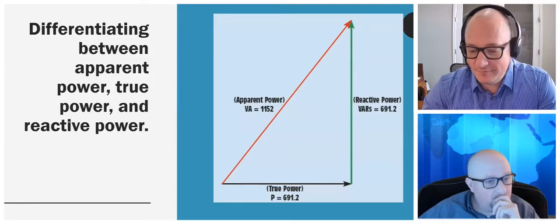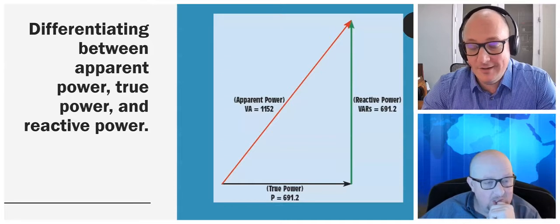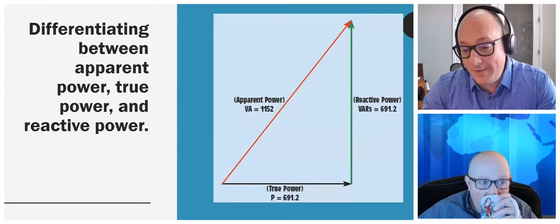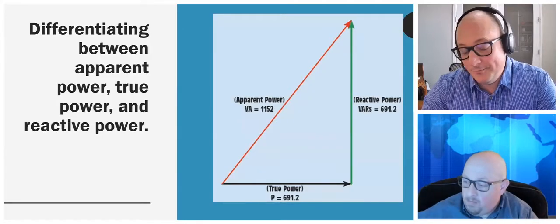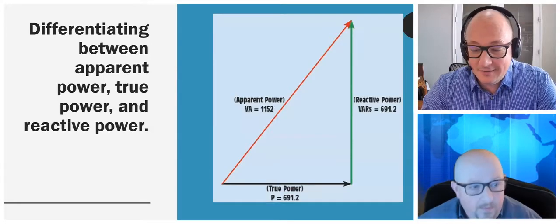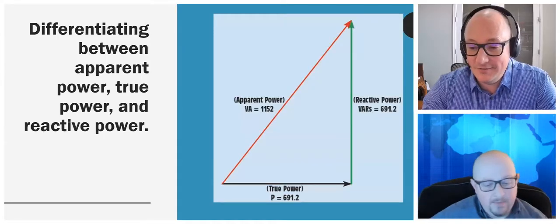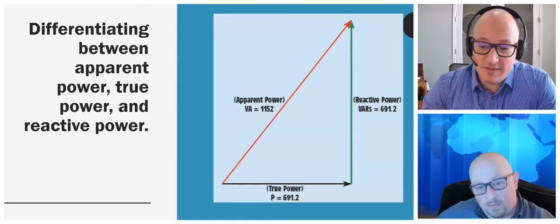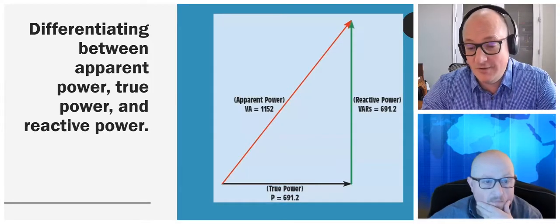Most of this is best explained mathematically, right? So we can look at some right triangle math because, depending where apprentices or students are at in their studies, we know that with the leading and lagging effect of voltage and current when there's inductive and capacitive components, or reactive components, the farthest voltage and current can be out of phase with one another is 90 degrees.